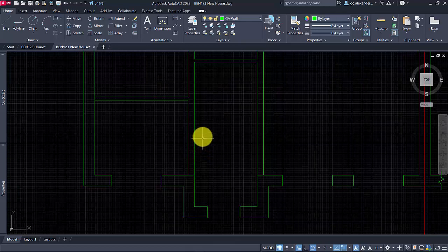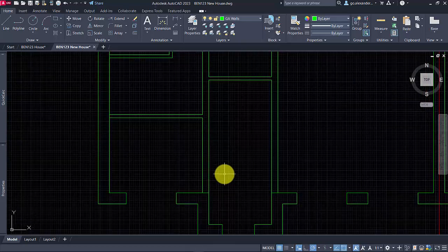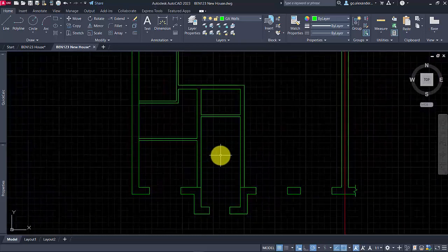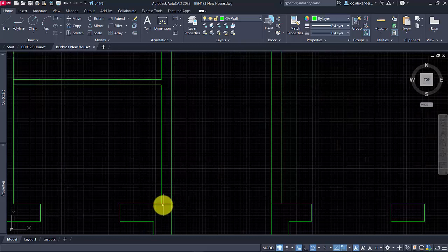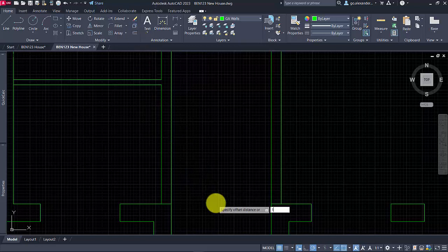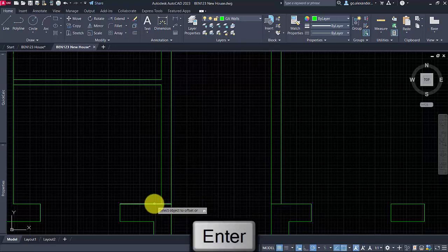What we can do is a few of the internal openings then for the doors, and then I can show the final version of the ground floor plan. So when you're putting in a door, we're going to use a distance of 910 millimeters, and we always want to offset that from the wall.